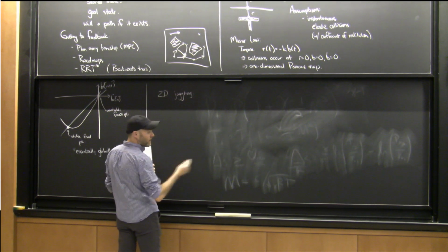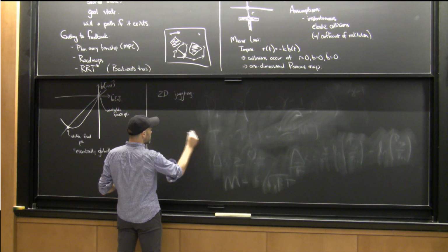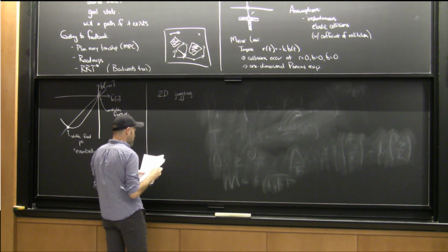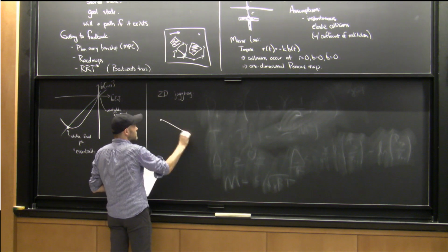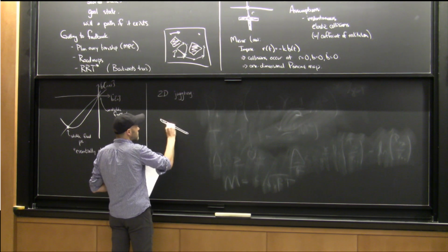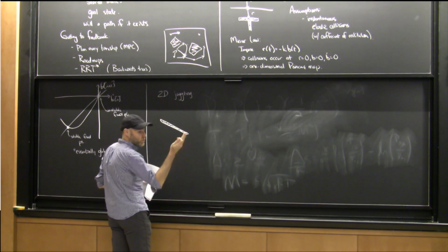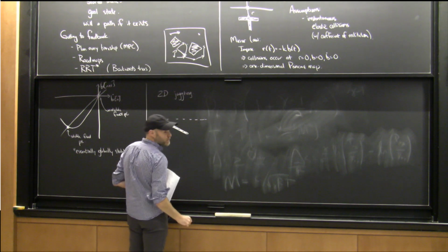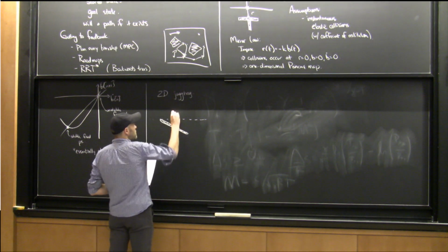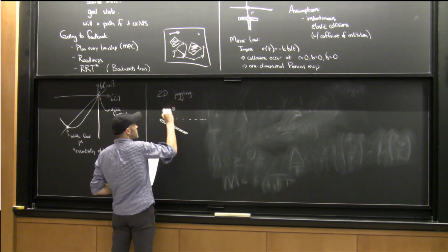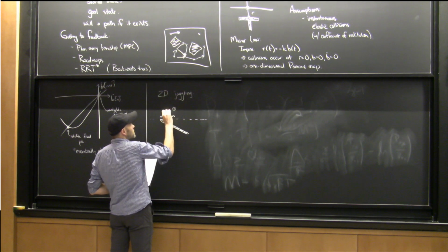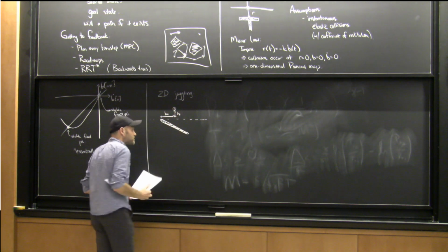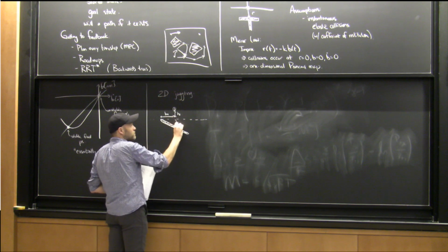So you want to allow the ball to move both in X and Z. It's going to go up and down, but also side to side. And it turns out you can do that pretty nicely in practice, even if you just have a paddle, still with one degree of freedom. I still have my place where I'd like all my collisions to occur, but now the ball is parameterized by the X position of the ball and the Z position of the ball, and the paddle is parameterized by theta.